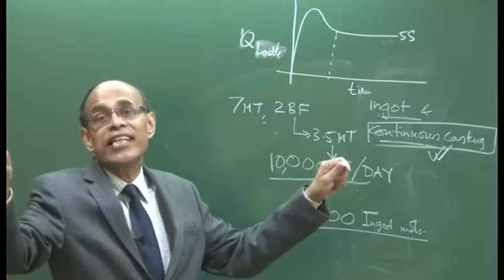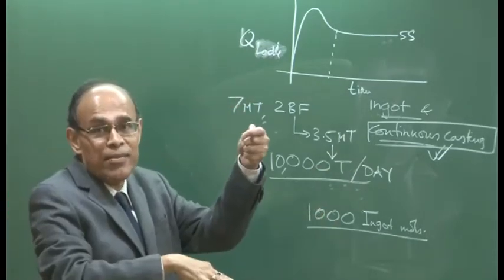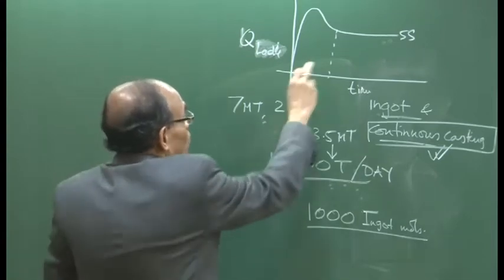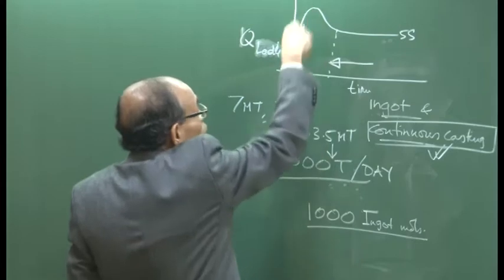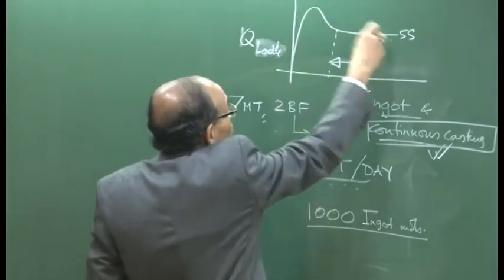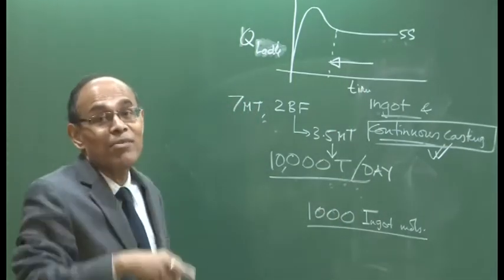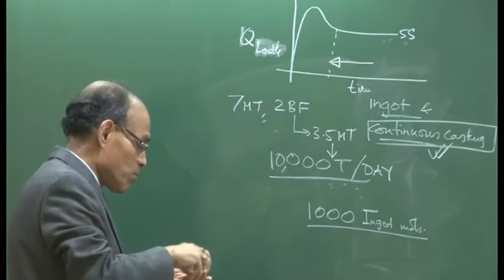So, nothing is changing in the tundish. The flow is stabilized, the bath depth is stabilized, the tundish weight is stabilized, everything is stabilized. So, beyond this point nothing changes, but initially this throttling is very important, and this is done deliberately, that you use more than the steady state flow rate, because our objective is only to submerge the shroud tip as early as possible.